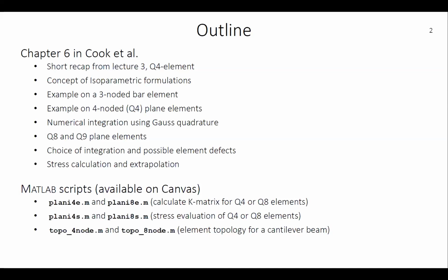And often, if you can find a case where you have an exact solution to compare with, you can accurately estimate the quality of your model. So you may often be able to solve the system, but if you use the wrong type of elements or the wrong integration order, you end up with rather poor quality of the results.